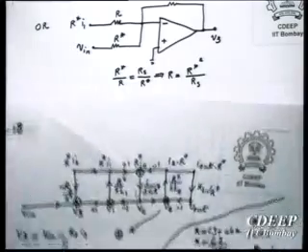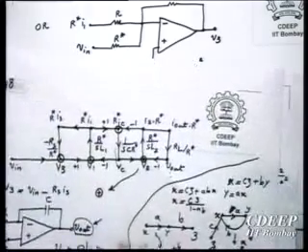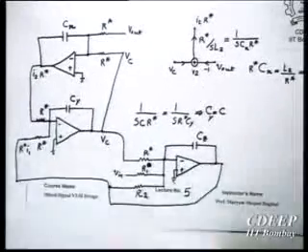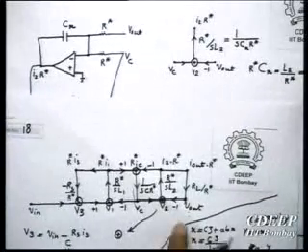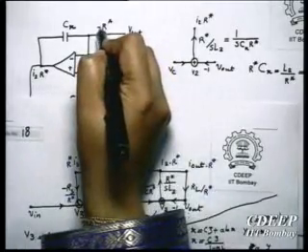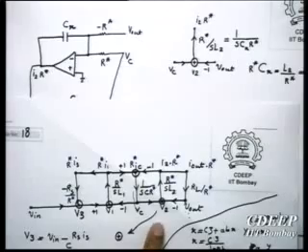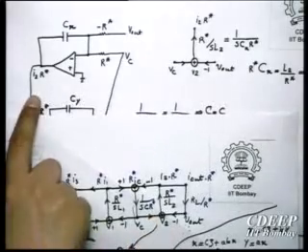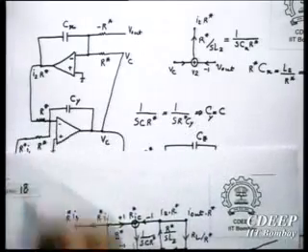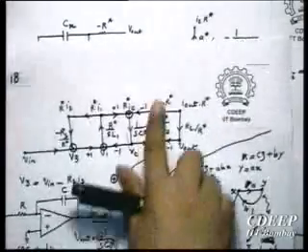And then V3 will come to the two-input integrator like this, so either this or this. Now we have to correct for this sign. Starting from here, V out was negative, right? Therefore this means this resistor should be negative. Then coming back here, I2 R star is negative when it comes here.